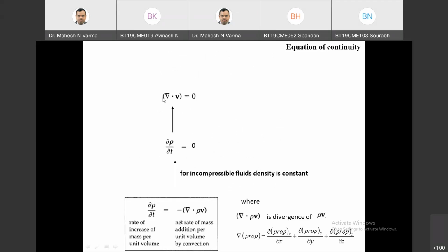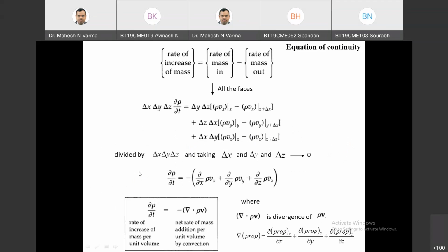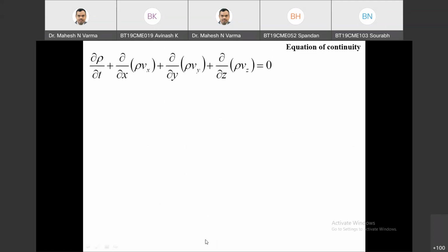This equation we have used, I think, almost in all the problems in shell balance equations, and in the first chapter also. When we were discussing the generalized Newton's law of viscosity, at that time we used it here. Because we are handling liquids most of the time, and liquids are incompressible fluids, this will be equal to 0, and you consider only the first bracket most of the time.